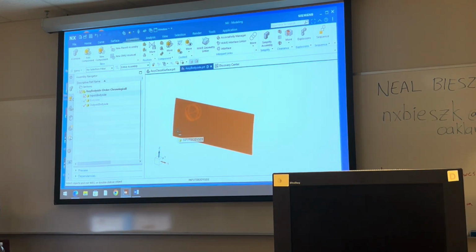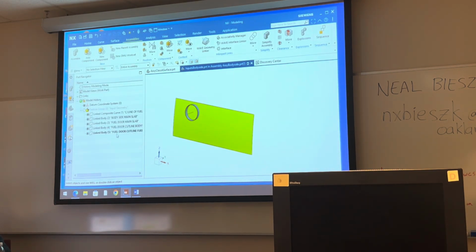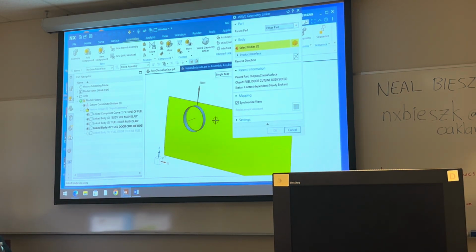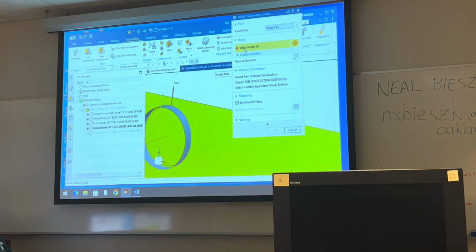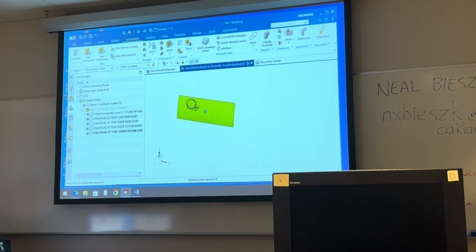If you don't get all green check marks, click on the one that doesn't work, right click, do a manually relink, and look at the name of it and point to the one that it's supposed to be, and that'll link it up too. Okay? You could even have gone through the inputs one at a time and double clicked on one, while you had the outputs of the Class A still here, and unselected what it was and picked the new one. That's manually relinking too. All right, anyway, I think I beat that one for a while. So I got them all working.